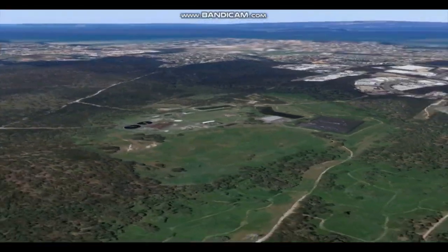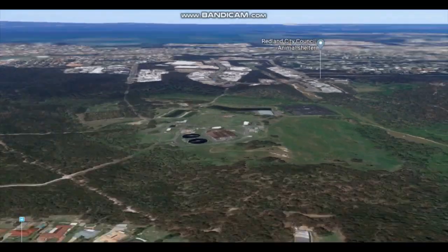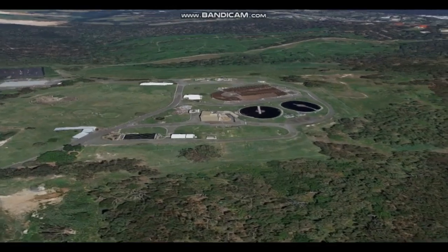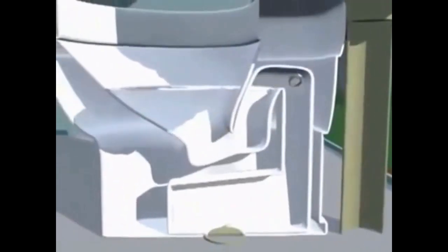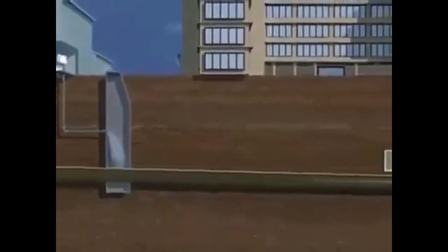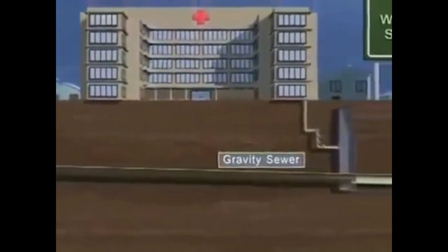The influent sewage has water parameters of total nitrogen level of 70.7, total phosphorus of 11.8, BOD 270 and COD 514. The plant was designed for 15 years and can be extended up to 20 years. The incoming water is basically rural, as most of the area is rural, and the waste generated is basically domestic.